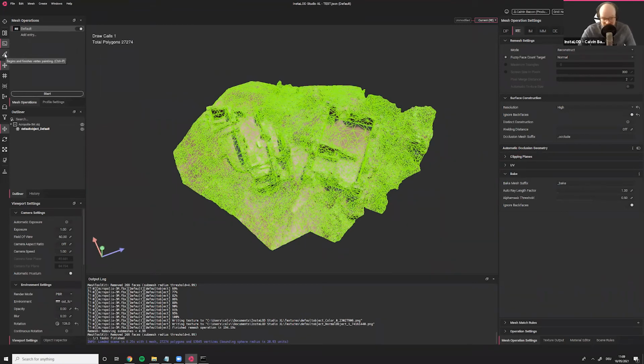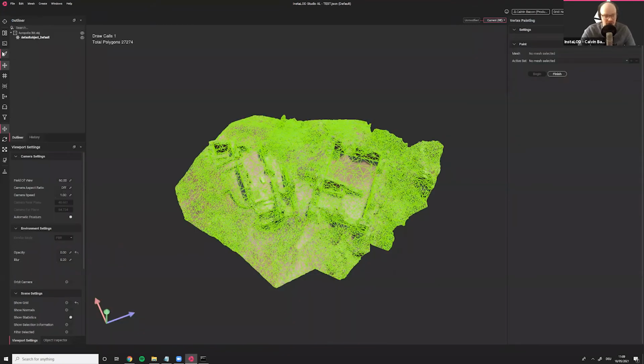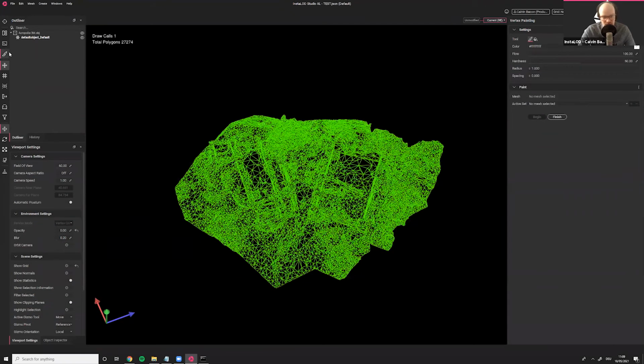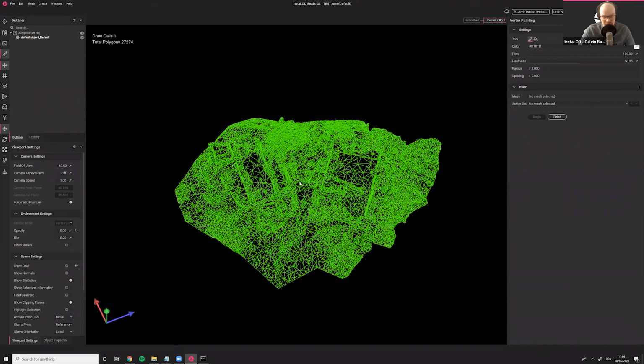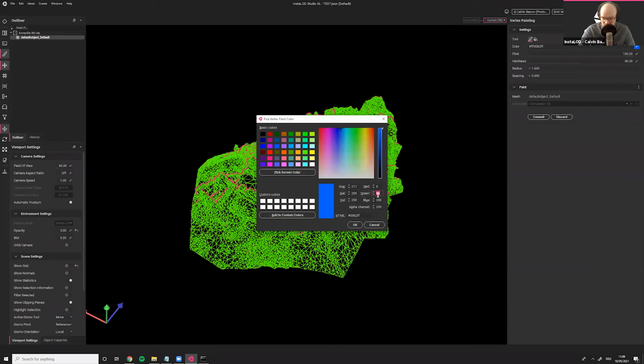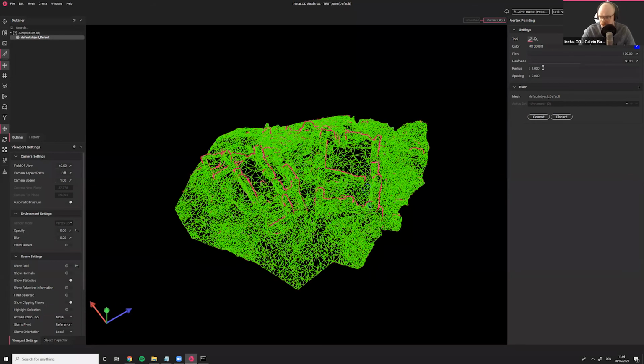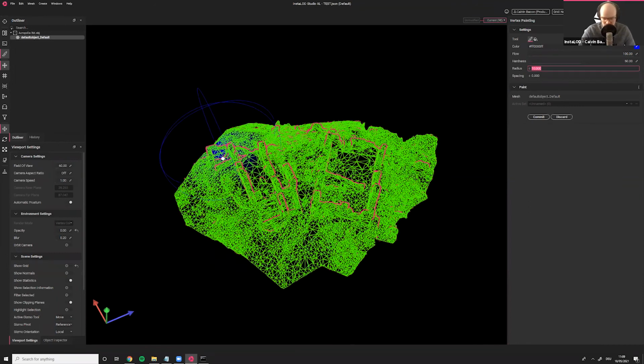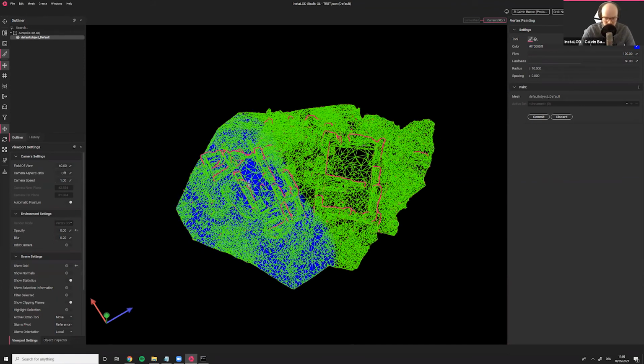We just use vertex colors. Okay, so in the vertex painting mode, which I can access by selecting this paintbrush, what I want to do is select the mesh, and then we're going to begin painting. So I'm going to paint with a blue vertex color channel. So the green channel is set to 0, the blue channel is set to 255. Let's just set the radius to 10. Paint one side blue, the other side we're going to keep black. And then we're just going to click commit.